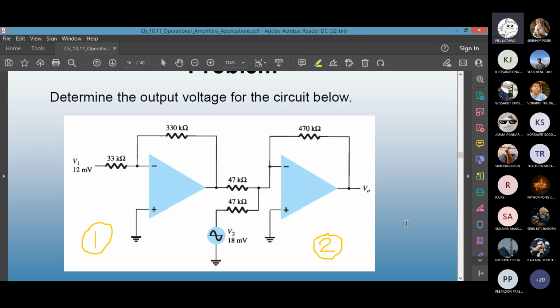It's an inverting op-amp. Inverting, yes, and summing. Summing op-amp, the input is given on the inverting pin. It is adding two different inputs. One is coming from this stage 1, and this is from stage 2 itself. Or we can say this is 1, 2, and then this one will be 3. That is also okay. What is the output voltage at stage 1?